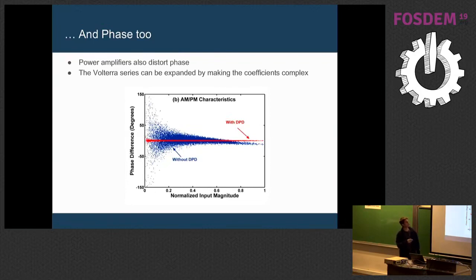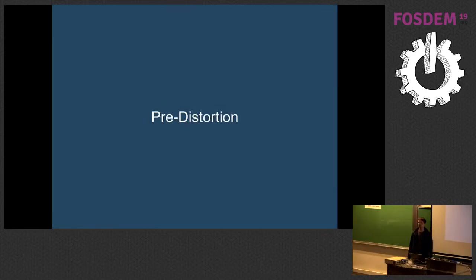The way you build that into the model is you just make the coefficients complex. So if you look at the flow graphs, which will be available for download, you'll see I'm using NumPy with the complex type. And so the original ideal model was just 10 plus j0, and the non-ideal has phase shifts to it.